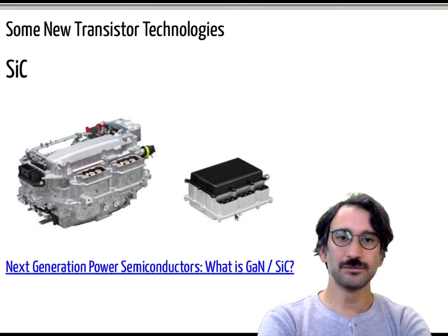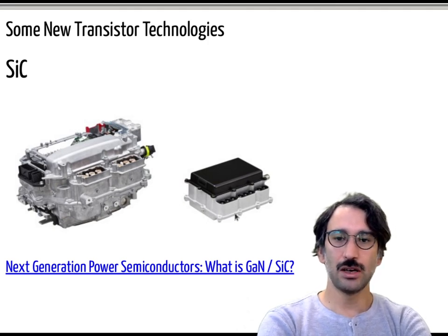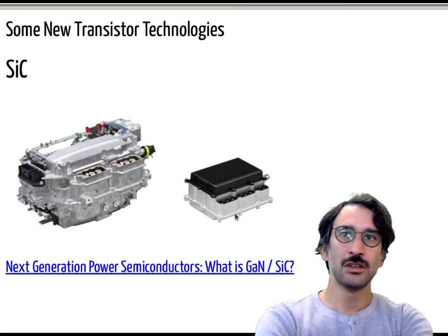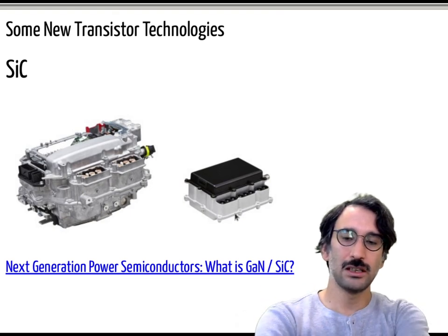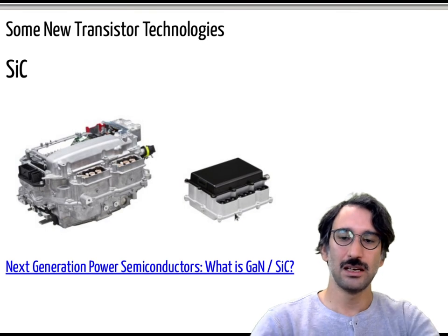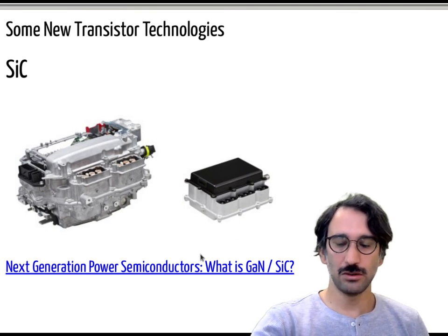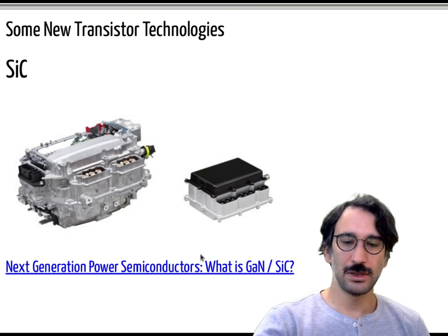And of course the idea is the same: silicon carbide devices are faster than IGBTs, so they can go up to higher frequencies, and higher frequencies help you reduce the size of the passive components, and switching losses are also low. Once you get rid of that thermal burden, you can make your transistors smaller. Please have a look at those reading materials, and they can give you some insight about the GaN and silicon carbide transistors.